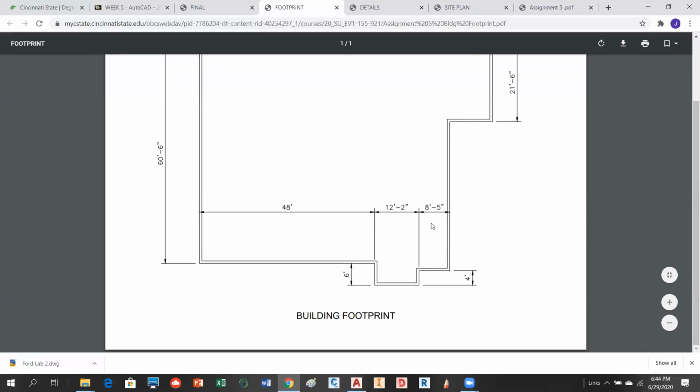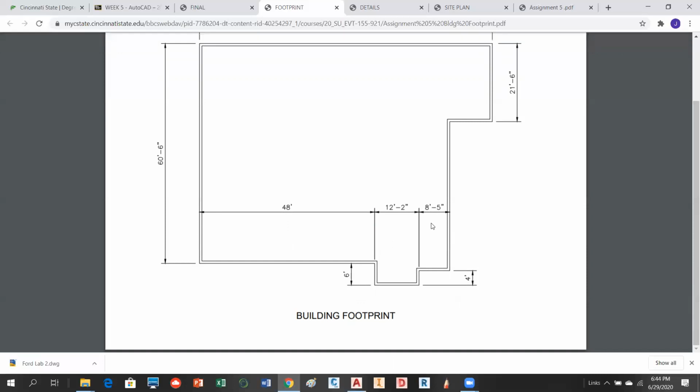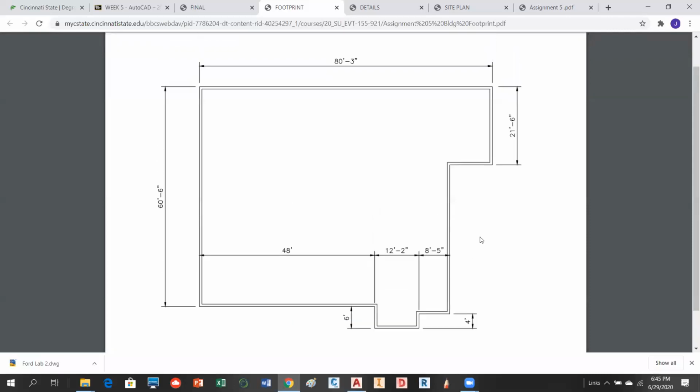If you take 5 and divide it by 12, it's not going to be a pretty number, okay? So what you want to do is make sure that you float these numbers out to like 4 decimal places, okay? So if you get a pure number like 0.5, you're good. But if it's 5 inches, make sure that you go out 4 decimal places. If you don't do that, it's going to give you a little bit of an error, okay? Not a big deal. You're only dealing with the outside lines here, by the way, not the inside, okay? Just the outside. Notice also you don't have this dimension here. You have to figure it out, but it's not tough, okay?